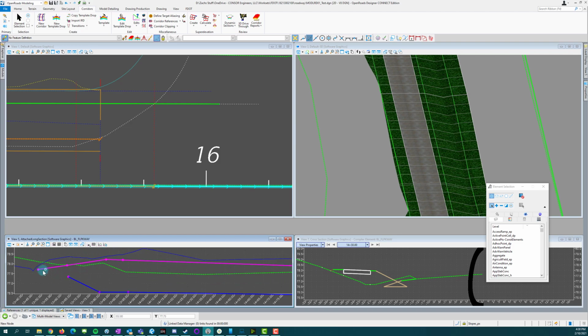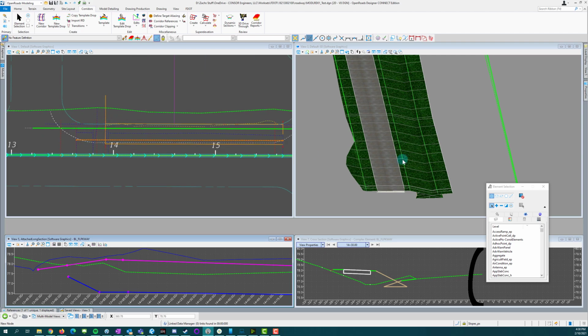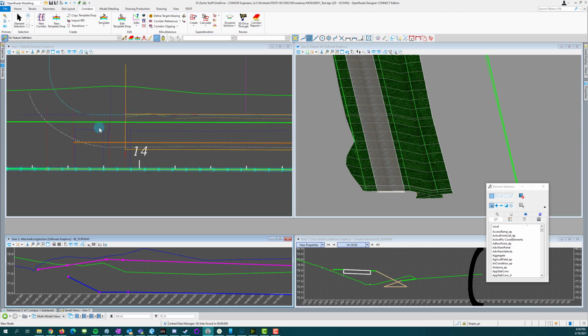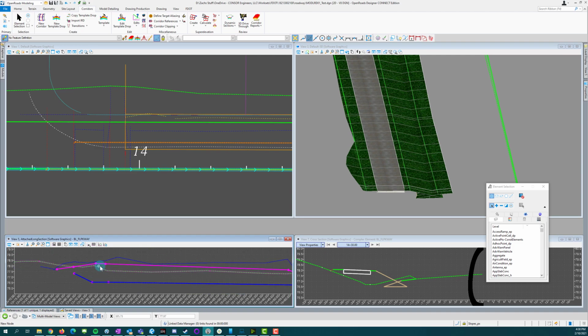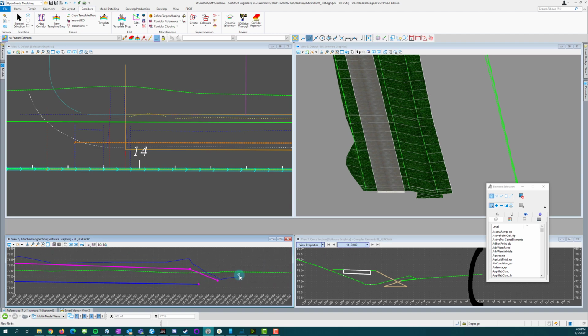So I feel like we are fixed here because of the existing ground. We're kind of fixed here. So this whole spot here is pretty fixed. So we haven't modeled that piece yet, but that one you might have to play with a little bit to get that one to work. But here we should drop this sidewalk down if we can. Maybe come off that another 20 feet or so, give that, and then come down here so we're a little flatter across here. So let me hop into the other file and we'll add that point real quick.